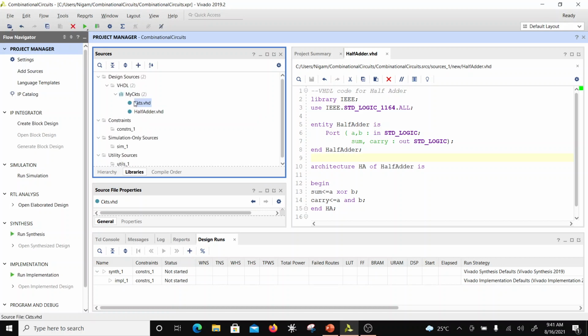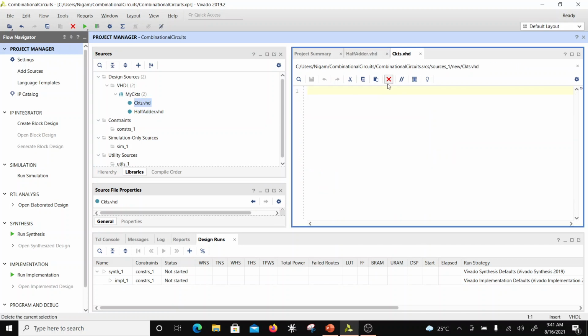Okay, so make sure that the package is the first thing it is going to see, and then there are going to be other files. So this basically is your my circuits library, circuits package, and this is basically your component. So here what I'm going to do is I'm going to open this file, double click it. Here it opens. Here also I need to include IEEE because whenever I do port declarations, it uses std_logic, and it will not know what is that.